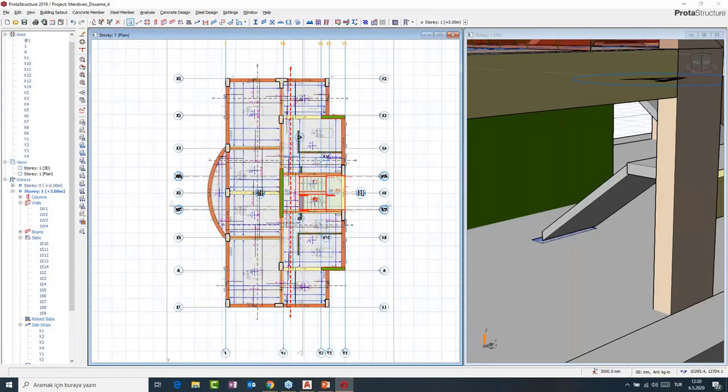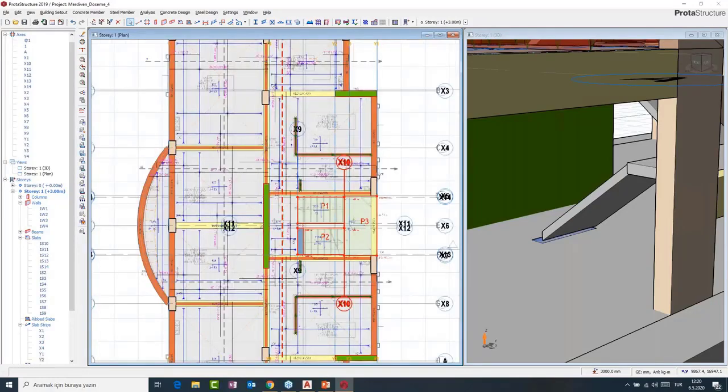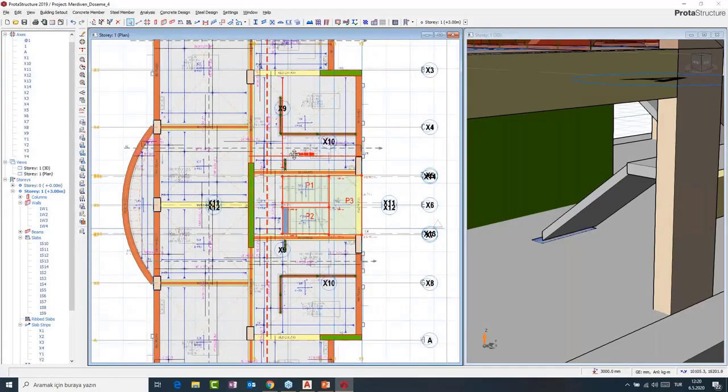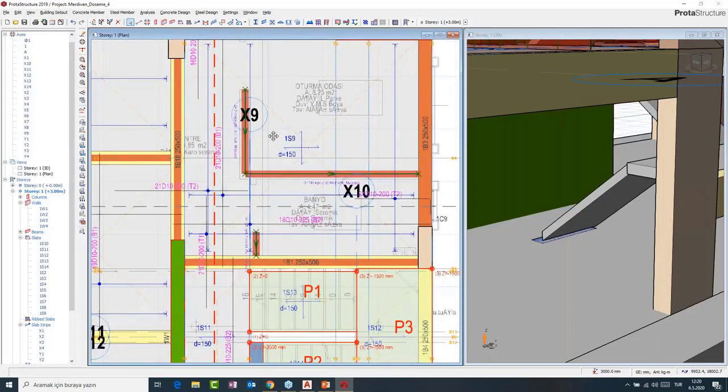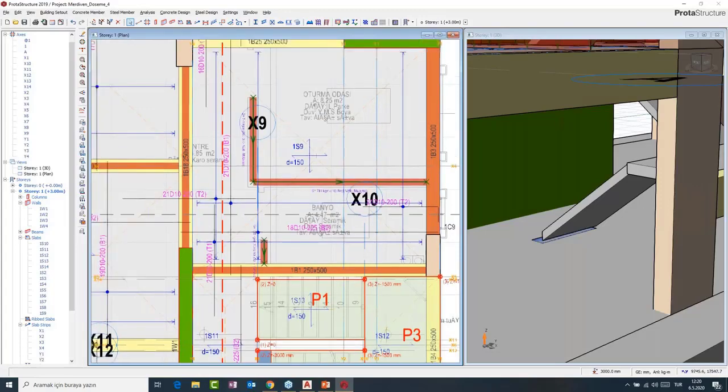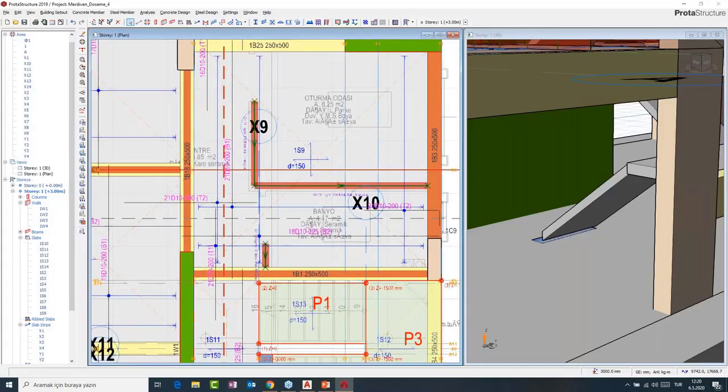You might ask, what's the difference between finite element strip and analytical strip? Basically, when you cut analytical strips, the calculation method in this case is that you can see these line loads here. When we cut an analytical strip, these line loads are divided into the area of this particular slab, and it is added to the dead load of the slab.